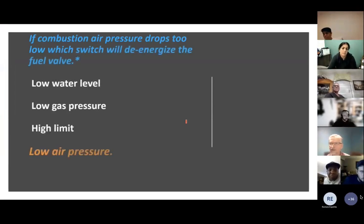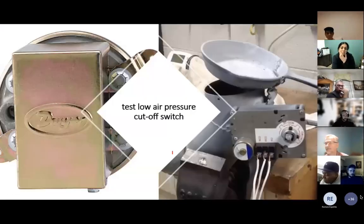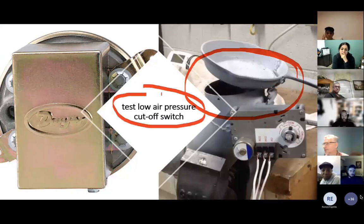If combustion air pressure drops too low, which switch will de-energize or turn off the fuel valve? The one we just looked at, the low air pressure switch. And a description of testing one of these: when I typed testing a low air pressure cutoff switch into Google, it came up with a video where a guy had an old frying pan and he put it over the fan outlet to test a switch.